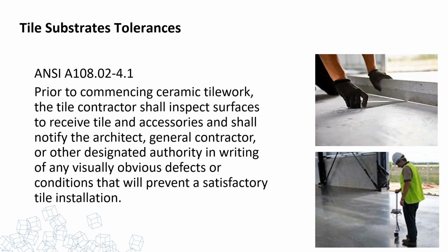The other flooring industries, vinyl, resilient, they're used to having floor prep done automatically on every project they go. Tile industry, for many, many years, we really didn't have to have that much of it. We had mosaic tile commonly going down in a bathroom floor in a commercial installation and wall tile. So we really didn't have a lot of floor prep. But today, with tiles the size that they are, surface prep is critically important.